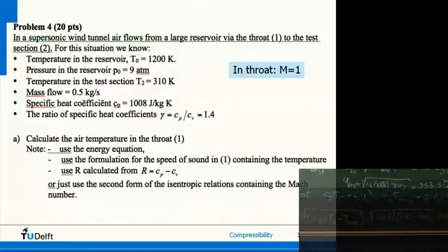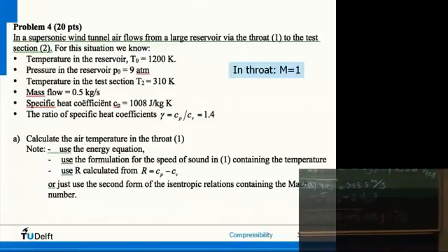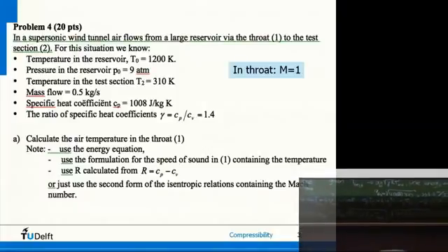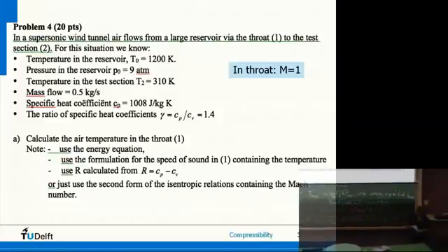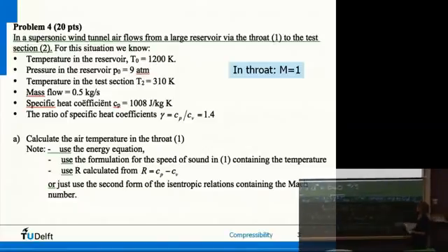So that you can accomplish, right? From 0 in the reservoir, due to the very high pressure in the reservoir, we can get to almost 1,400 meters per second. Almost there, because the question was the Mach number, right? So for the Mach number, we have to divide V over A. I'll do it up here.